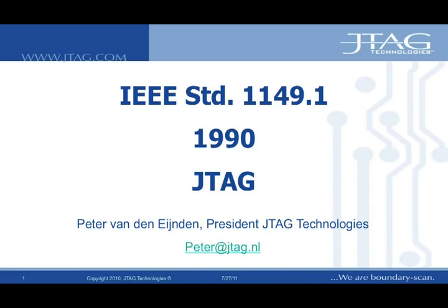IEEE Standard 1149.1 provides an elegant solution to this problem. The standard was developed by an international working group of electronic companies called the Joint Test Action Group, or JTAG. Hence, IEEE Standard 1149.1 is still often referred to as JTAG. The standard's official title is IEEE Standard Test Access Port and Boundary Scan Architecture. Since its release in 1990, many extensions have been defined in additional standards covering different signal types and applications.